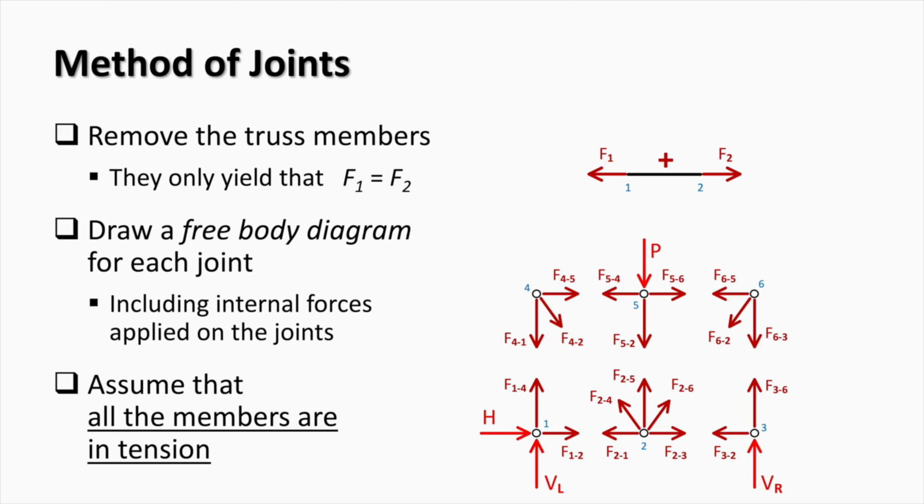This means that we assume that all internal forces are initially positive and directed away from the joints. Compression forces will be represented by negative values, which corresponds to the adopted sign convention we discussed earlier. If the direction of forces in a compression member is not updated, the compression forces appear automatically.